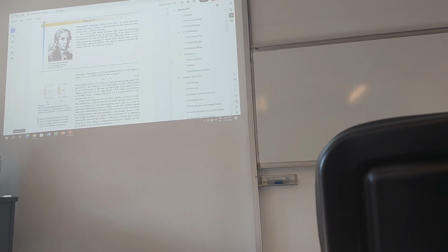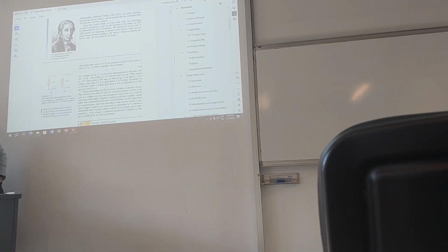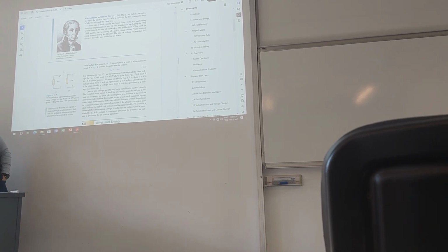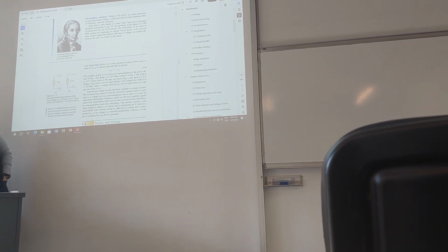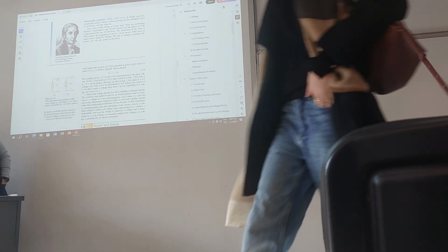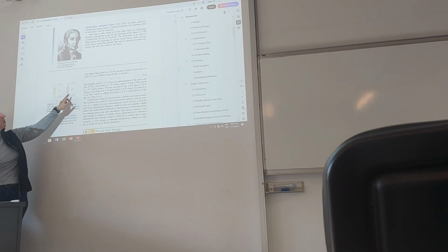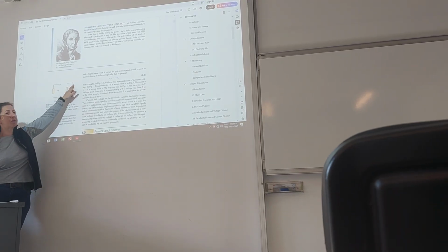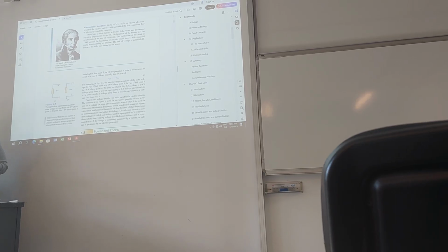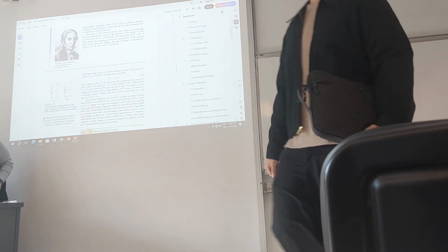So we have talked about this. In general, this might be representing anything in our electrical circuit. It might be a resistor, a potential source, it doesn't matter. The idea is, if they are the same thing, and we are trying to calculate the potential difference between point A and B, this one and that one are exactly equal. Here A is the plus sign, so if the potential difference between B and A is 9 volts, then in this case, if this is plus and this is minus, the corresponding potential difference is going to be minus 9 volts. So you should realize that just changing the polarity only changes the sign in front of that number.